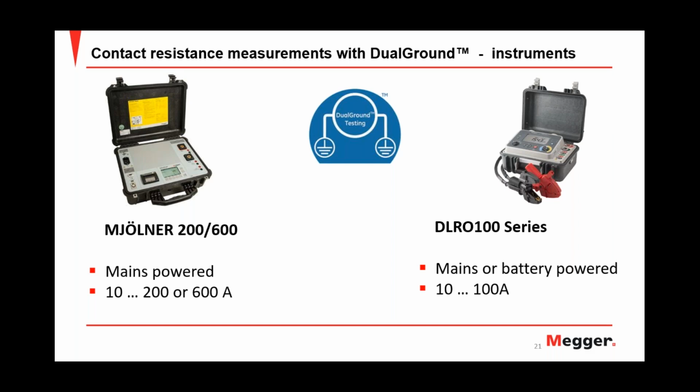And we have the DLR 100, up to 100 amps, which can be mains or battery powered, with enough energy in the built-in batteries to inject 100 amps for around 20 minutes. So more than enough for days of circuit breaker testing. Both instruments will inject pure DC with down to 0.1 micro-ohm resolution.